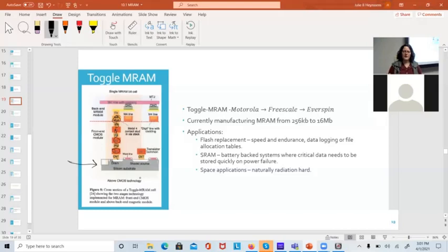It's 4 layers of metal up. So I've got, you know, good micrometer distance up on top of it. And then I take this thing that I have produced on a standard CMOS line, and I give it to another foundry that's going to put the magnetic materials on there and process that. So this is a single MRAM cell, this orange area right here. And it's vertically relatively tall, but it fits in the same size as a single transistor.